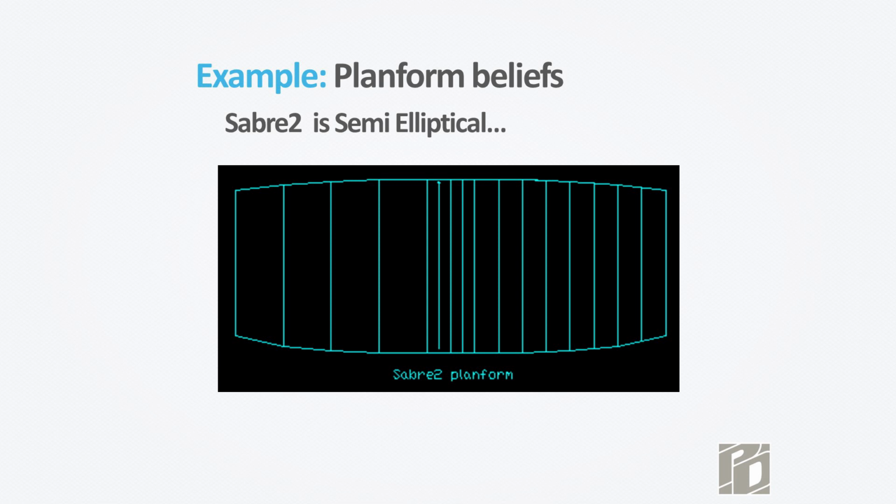And that is considered by most people a semi-elliptical canopy, and most people have an idea of semi-elliptical being a canopy that's, not a student canopy necessarily, but good for novices, all round, blah, blah. If you want to have high performance, you really need to get past a semi-elliptical parachute and jump something that has more power and more punch, and to do that, you've got to have at least a fully elliptical canopy, if not a cross-brace canopy, like a Velocity.